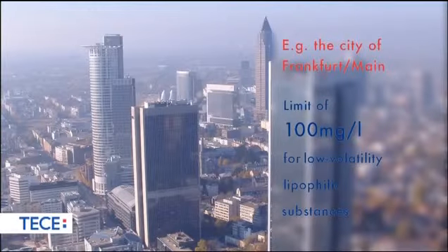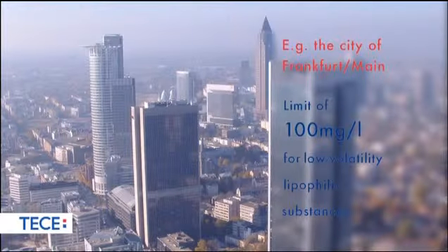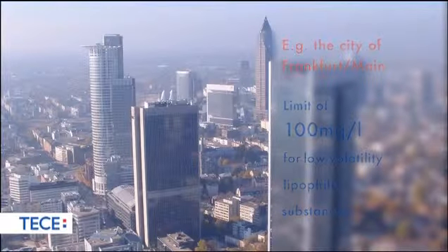For the city of Frankfurt, for instance, a limit of 100 mg per liter applies for lipophilic substances in wastewater containing grease that are discharged from industrial or commercial operations. Yet conventional grease separators conforming to DIN EN 1825 or DIN 4040 Part 100 in most cases cannot meet this limit.